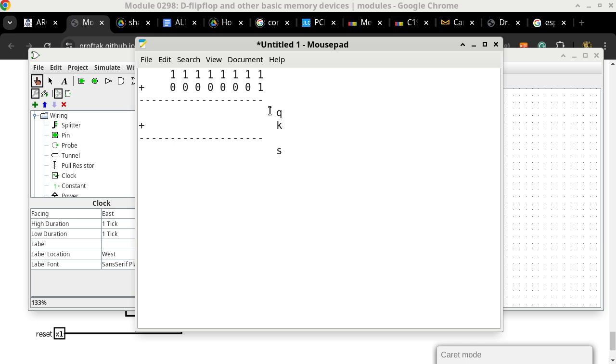Q is not even dependent on whether we're adding or subtracting for binary. For bases other than two, how the Q row is computed from X and Y depends on whether we are adding or subtracting. But for binary, it's the same. It is basically just the exclusive OR between the X and the Y.